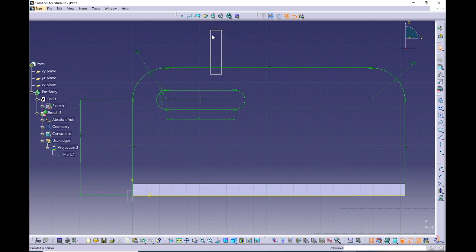And now let's take a look at mirror. We're going to mirror the slot over to this side. We could have done another slot, but hey, let's go ahead and practice a mirror. So first I need a line of symmetry. I'm going to use the line command, and I'm going to pick the midpoint. See how the circle fills up, letting me know that's a midpoint. And click.